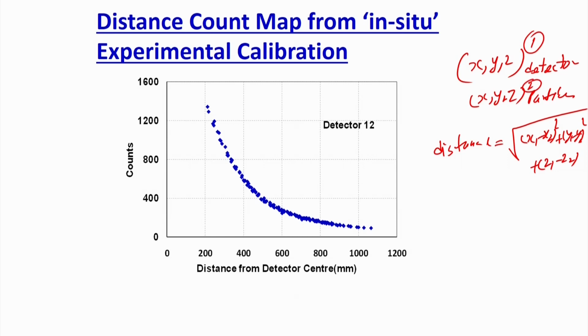So what I will get is how, with the distance of the tracer particle from a particular detector, the counts on that detector are changing, and as we know it is going to follow I equals I naught e to the power minus mu L. You can do the calibration and validate whether it is following or not, and you can see that it is following that curve, a bell kind of curve or a Gaussian curve, which shows that it is following the Beer-Lambert law.